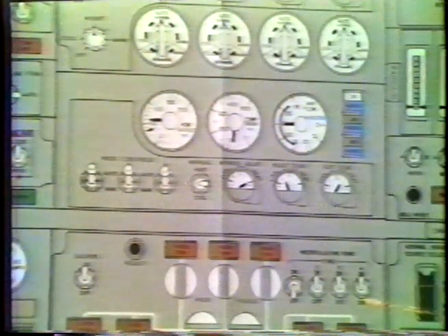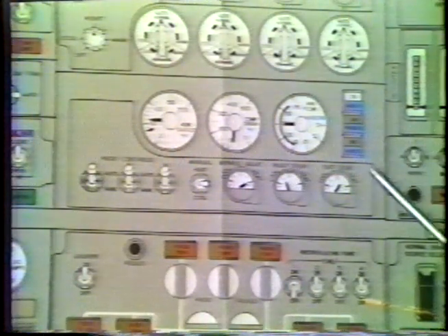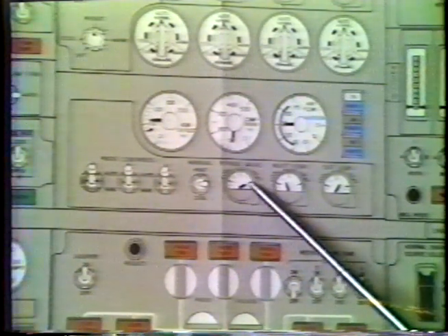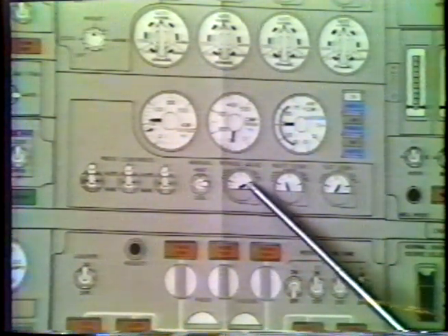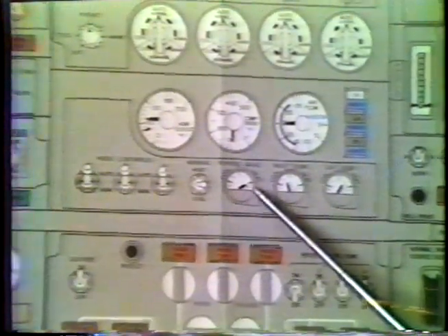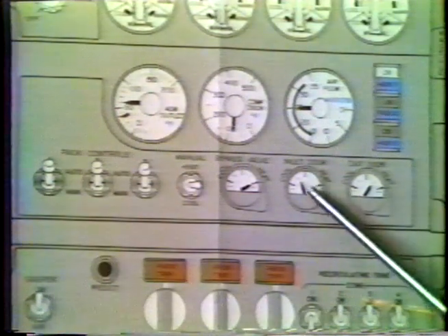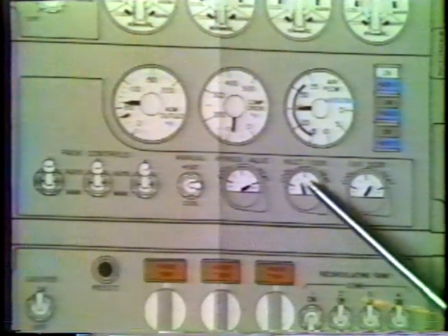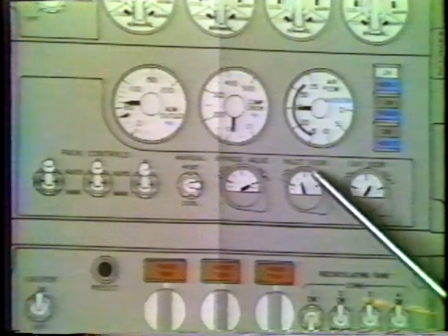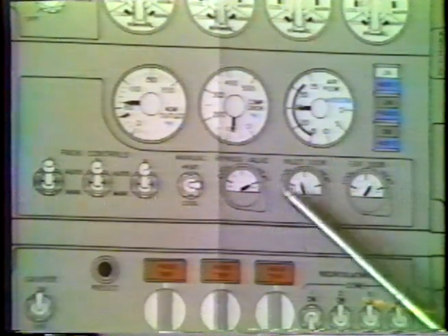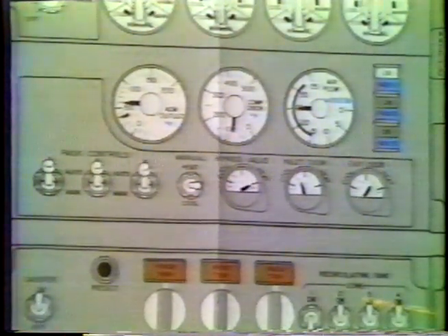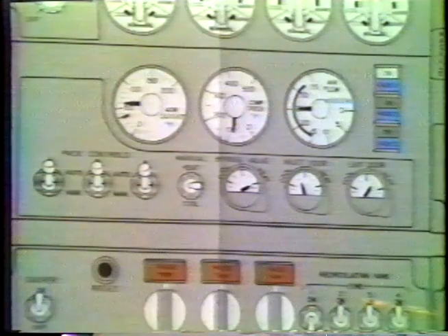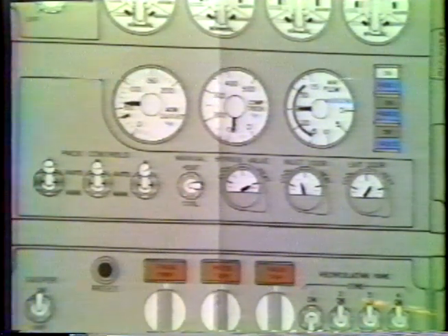What is supposed to happen when you're providing air to the cabin, the temperature is controlled by the bypass valve until it reaches full heat. Only when it reaches full heat, then the air is controlled by the inlet door by going from cold or cool towards the heat or closing down. If the inlet door starts moving before the bypass valve is in full heat, then that would say the valves are out of sequence and cause a pack trip.